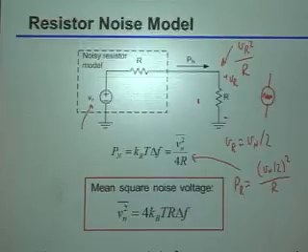Now, let me maybe ask you guys a question, similar to what we discussed before. In this expression with noise voltage, what can you actually control? What's your degree of freedom to play around with? The bandwidth and the R. Yeah, okay, so you said basically only the bandwidth and the R. Now, by the way, oftentimes the bandwidth is going to be specified by things that you can't control either, right? So there's a certain speed of signal you're dealing with, or a certain variation you're interested in. Oftentimes the bandwidth is just going to be spec'd by the system you're trying to build in the first place.